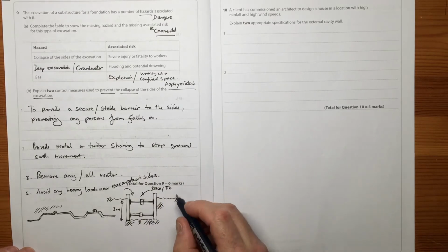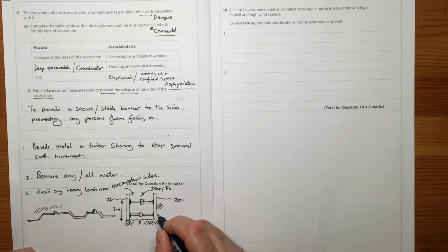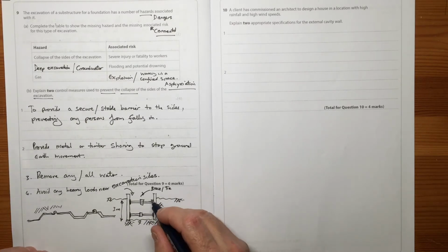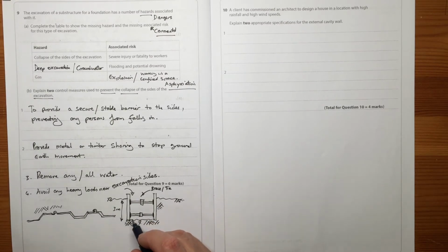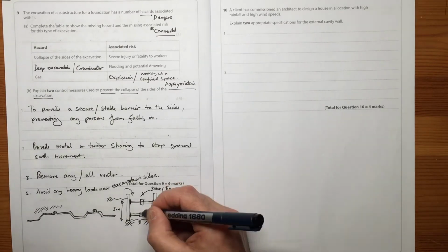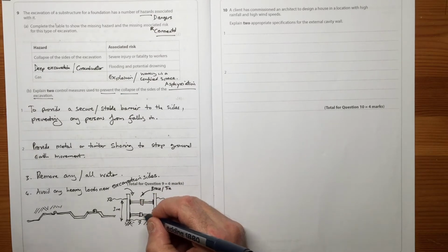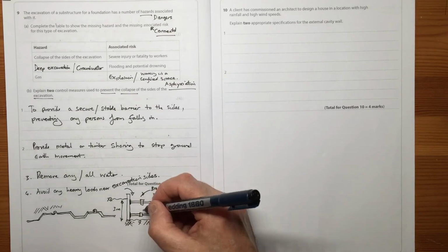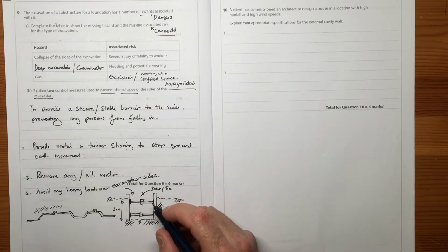Really important. You've got a big lorry here. It's going to try and force some of this load and perhaps break off a lot of the earth and force it into the hole. And it does happen. Another way to prevent it, when you've dug the hole, try and fill it with what you need fairly quickly. If it's going to be a concrete mass poured foundation, just fill it and then you remove the danger straight away. Okay, that's a way of avoiding trench collapse as well.